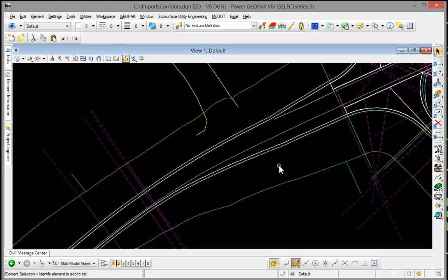But having said that, the theme of this particular demonstration is all about optimization. So what I want to do is to provide an example here. Let's say that we are targeting an existing edge of pavement to differentiate between overlay and widening. And that edge of pavement may be made up of literally thousands or tens of thousands of PI points. Well, what happens when we target that feature, in the way the program is written right now, is that it will have to scan those particular alignments or those edges multiple times for every cross section to find out does it exist in any particular given file.